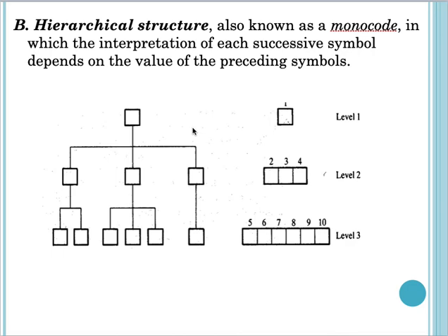The hierarchical structure provides a relatively compact structure, which conveys a lot of information about the part in a limited number of digits. The first digit, 0 to 9, divides the part into major groups such as machine parts, cast parts, forged parts, sheet metal parts, etc.